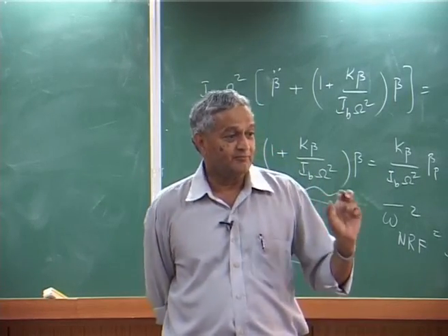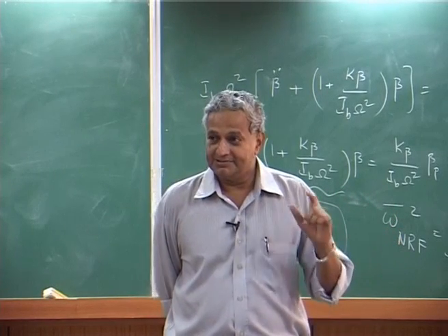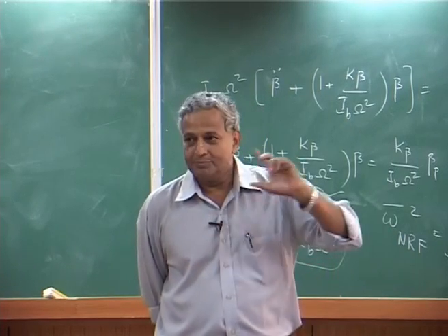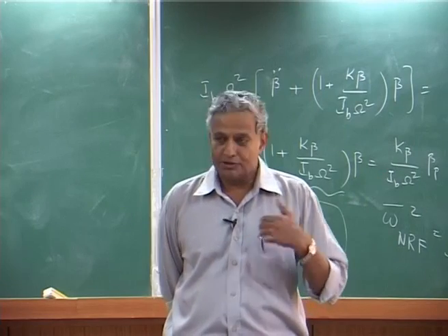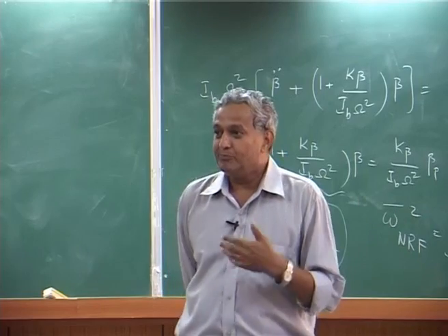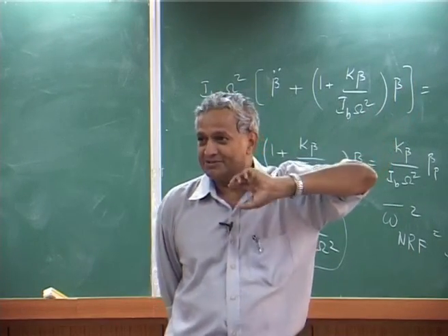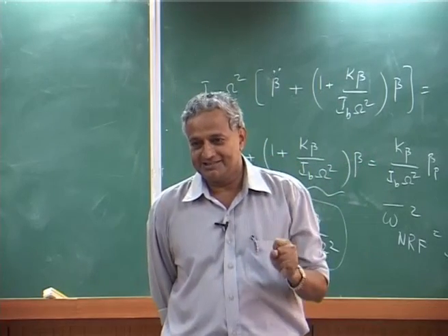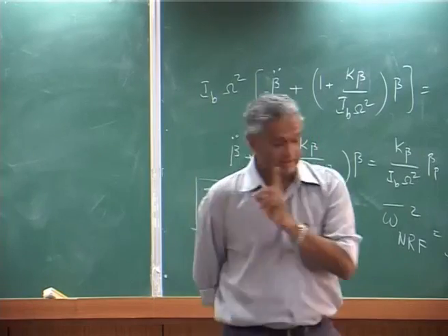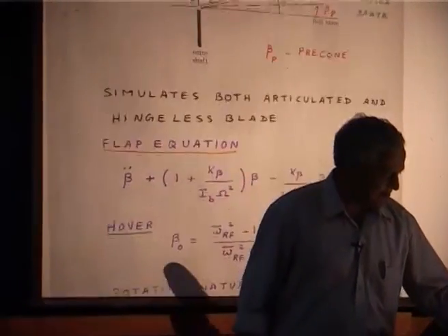What should be my flap frequency? It is really challenging, because this is going to affect my performance, control characteristics, my loads, hub moment, many quantities. That is why the flap frequency is a very dominant frequency. That is the first flap natural frequency. We will come to that influence part later.